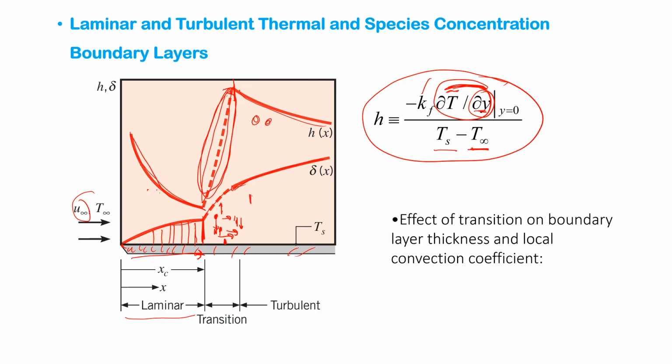So you always have now the motion in y direction. All of these striations, all of these fluid molecules in this region will have a strong mixing in y direction. Now, again, this thickness is increasing. That means this delta y is increasing. So this means this derivative is decreasing. So that's why you have a decreasing trend again. Okay, so these are the reasons behind this complex looking behavior here.